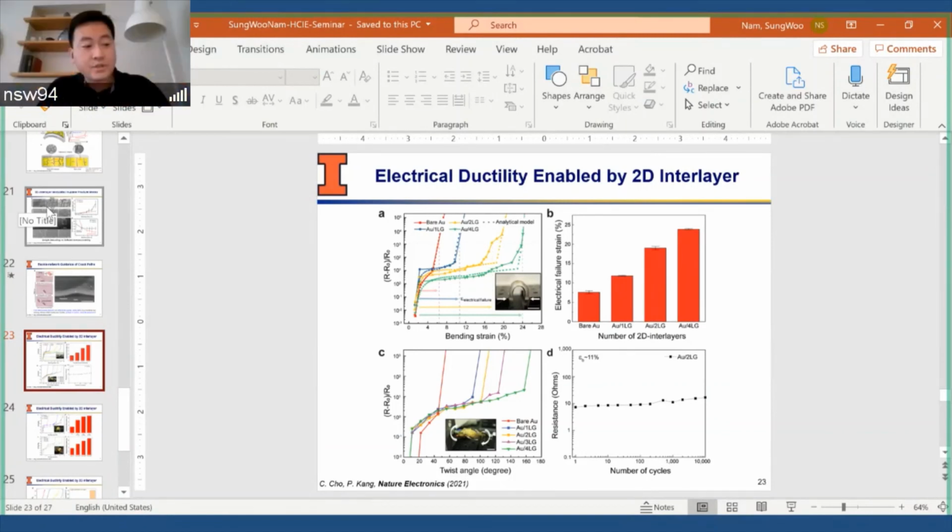Right. I think that's a very interesting question, and I think the short answer is yes. If you think about traditional crack formation, you start from some sort of stress concentrator. A few years ago, people used that kind of notch-type predefined feature, upon bending, to start creating and controlling cracking on metals on soft substrates. So that's a well-established understanding.